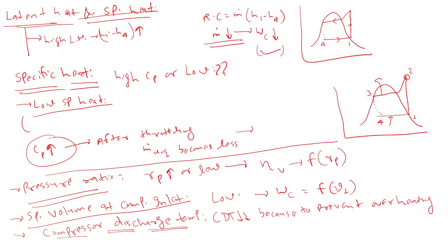Sir, but if discharge temperature is high, then more heat rejection will occur, so work will increase. In the whole system we provide insulation, let's suppose a polymer whose melting point is close to 60 or 70 degrees Celsius. Now if the compressor discharge temperature is 70 or more, it will try to melt that system.